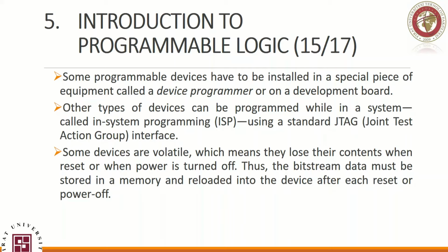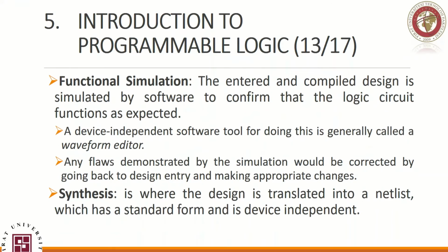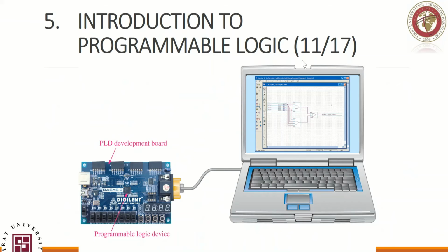Sometimes we said that we have a program. Once we create this, like this is my design, look at this small part. This is my design. I compile it. I transfer it to a bitstream. I create my own program. I want to download it now. Now maybe the PLD itself has a volatile memory. That means once you turn off the electricity, whatever is on the programmable logic device goes off.